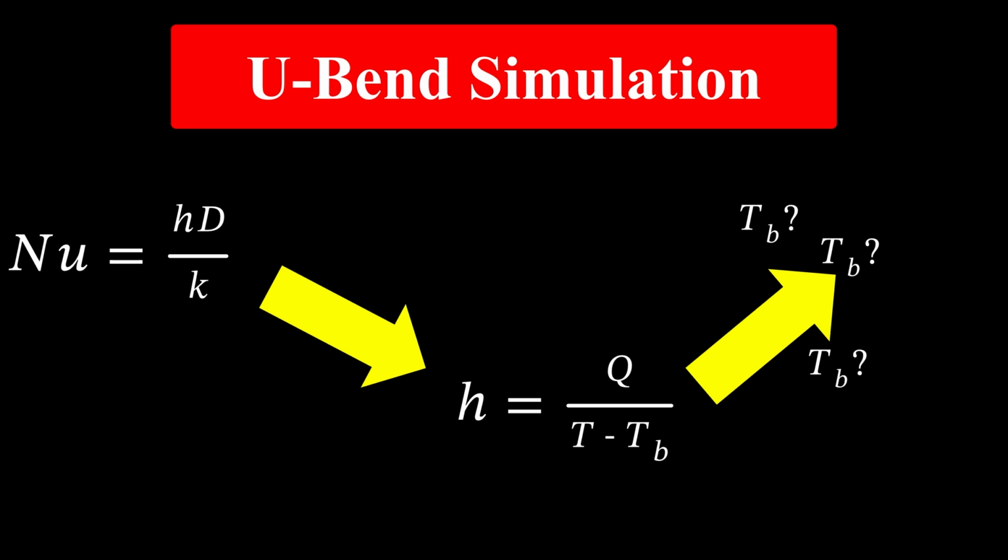If you are looking to get the Nusselt number, you must know that this number can be averaged or locally dependent on x. For both, you need to get the heat transfer coefficient first. To get the heat transfer coefficient, you need the bulk temperature. Q and T parameters in the formula are extracted from the simulation. In most cases, Fluent software doesn't report the heat transfer coefficient correctly, and you have to extract this coefficient manually.